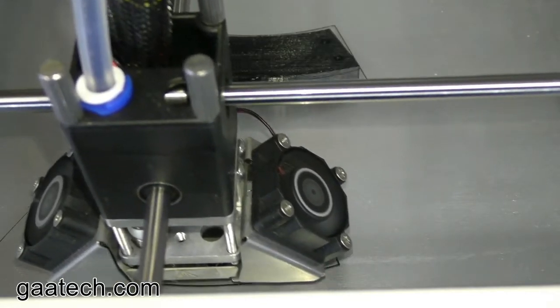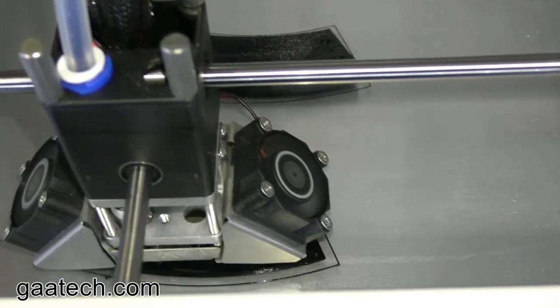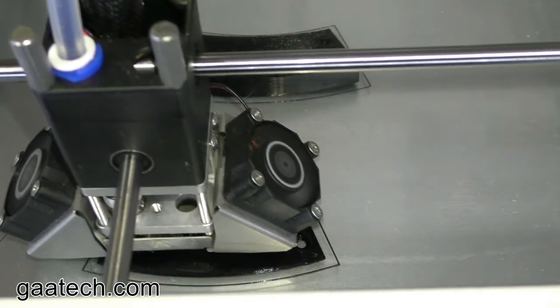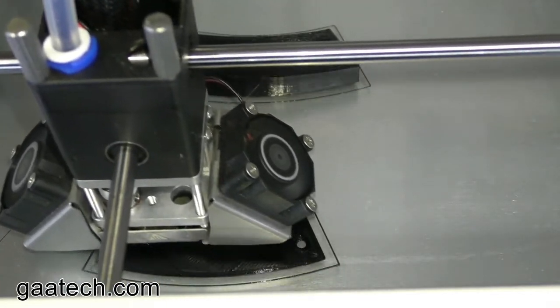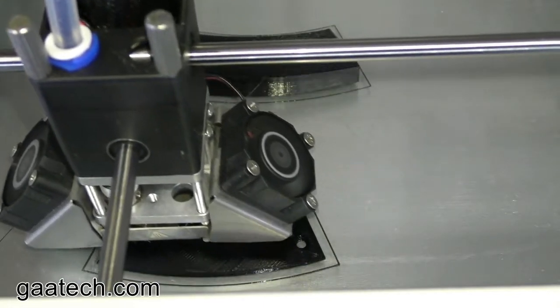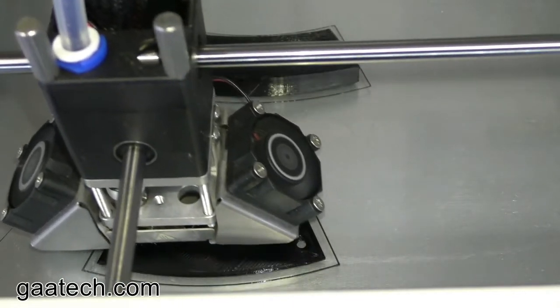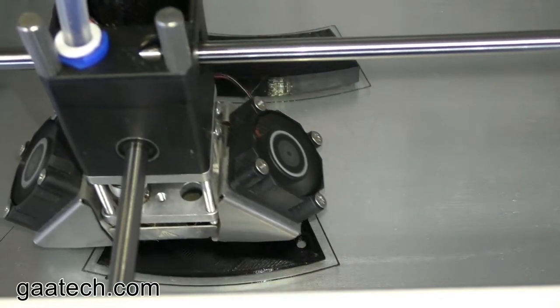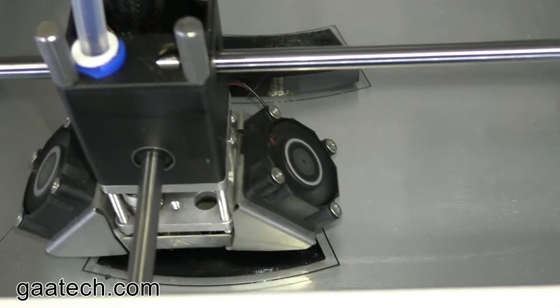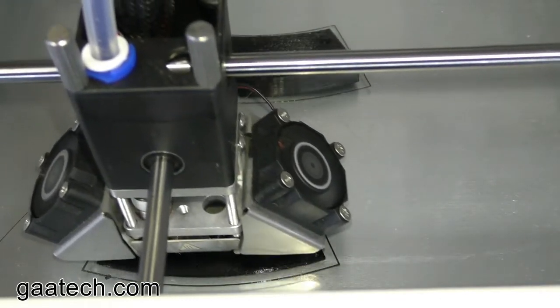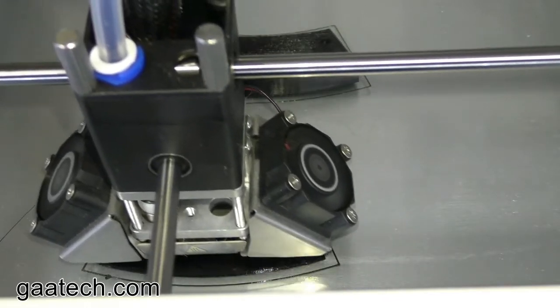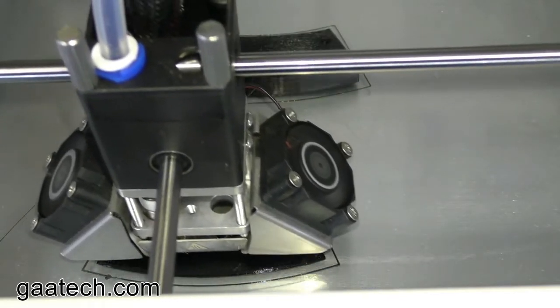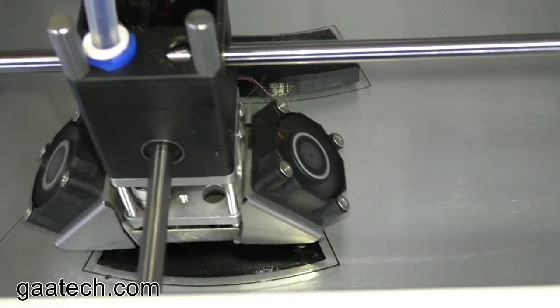And you can see this time the printer's now laying the next layer opposite to the first layer, so that's what makes it stronger. So just sort of a weave like carbon fibre, the greater the orientation, or the greater the layers are opposed to one another, the stronger the base layer will be.